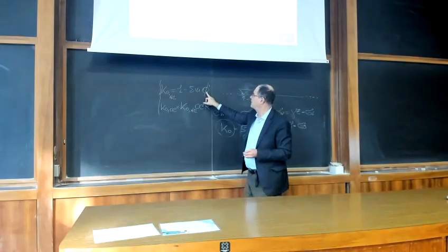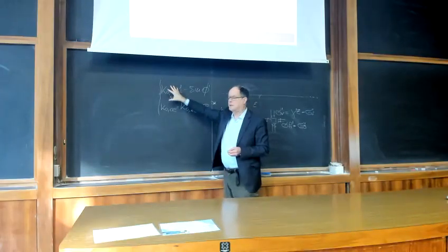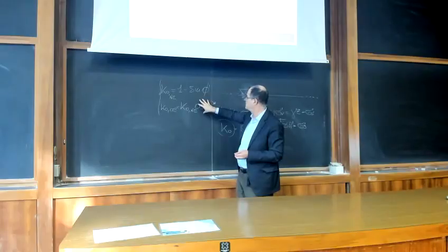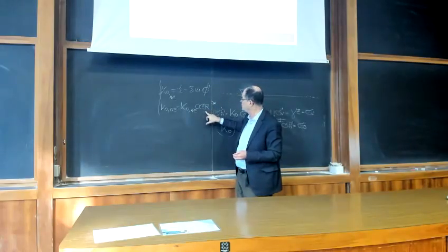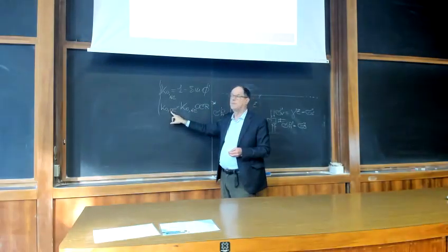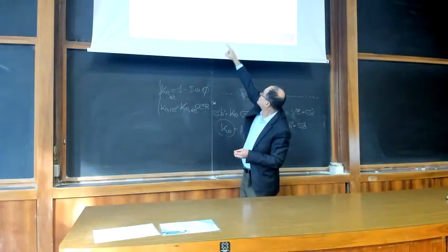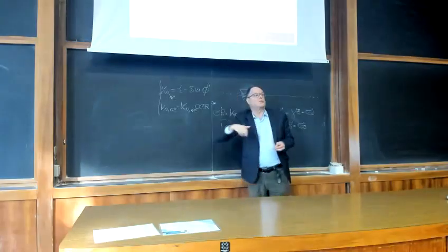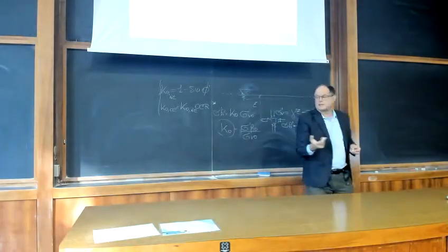This is a positive number, so this is definitely less than 1. But if you multiply by a positive number elevated to an exponent, this becomes greater and greater with OCR, and this can become greater than 1. So this means that your stress state goes on the other side, and you have a horizontal stress which is higher than the vertical stress.